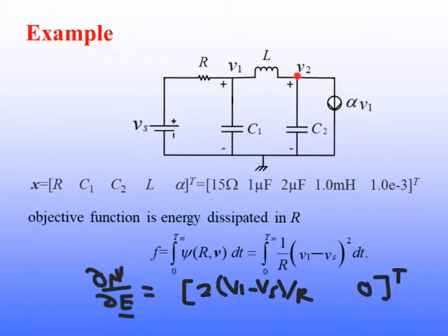So you do the same here. You say that this current plus this current plus this current is equal to 0. This current is alpha V1. This current is C2 dV2 by dt. This current will be equal to 1 over L, the integral from minus infinity to t, of (V2 minus V1) dt. After you write the equation, you differentiate both sides to get rid of the integration. So you end up with a second order differential equation. Both KCL equations are going to end up giving you a second order differential equation after we differentiate once to get rid of the integral coming from the inductor.